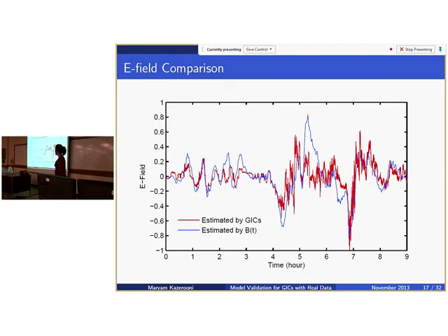There are many factors that contribute to this mismatch and the model accuracy. The most important one is that we're measuring the GIC at substations near Wisconsin and Michigan, but we're getting the magnetic field data from Fredericksburg, which is quite far from the Wisconsin area.